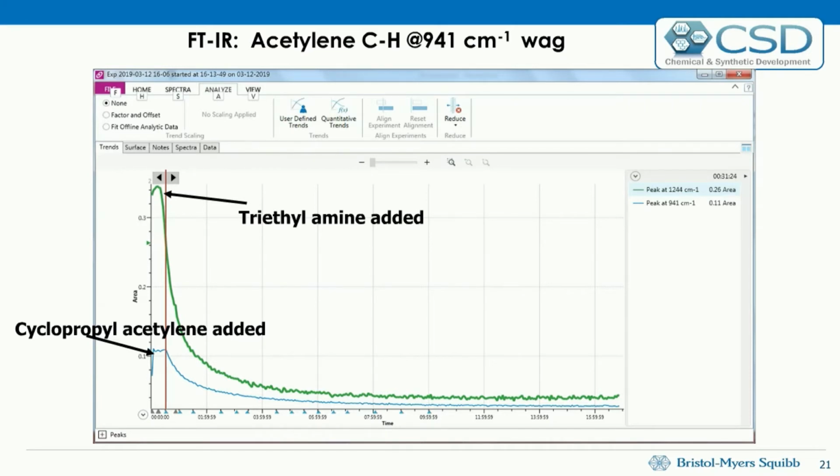Initially, many times reactions tend to run overnight or throughout the day. By doing the simple aspect of putting a probe in a vessel, you can follow the kinetics of it and determine, yes, my reaction can be done in 6 hours or 4.5 hours. So it gives you a lot of the kinetic profile, and that's important for us in both final product and also intermediates.